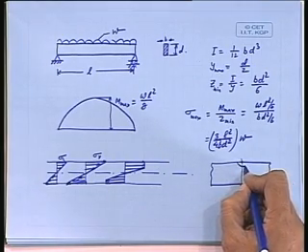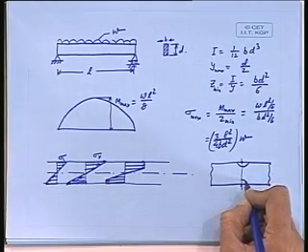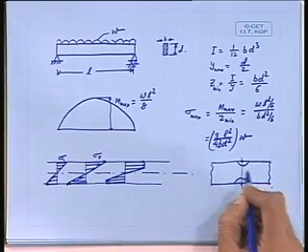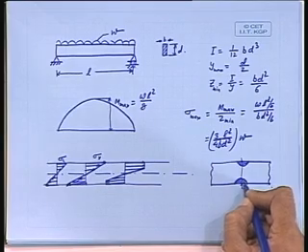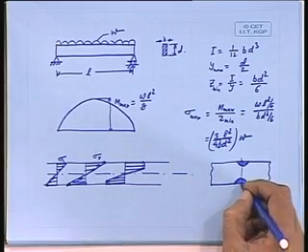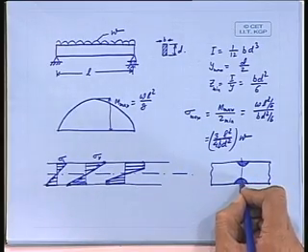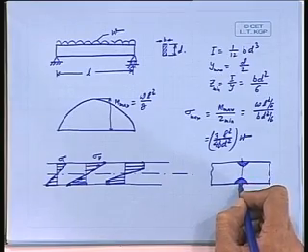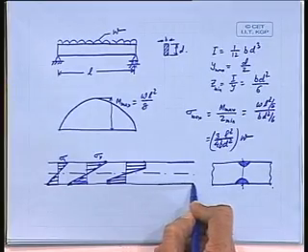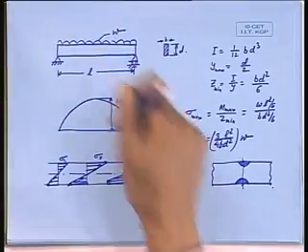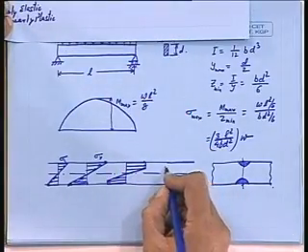Now it has penetrated down to some level and all this has become plastic region having the same stress value of sigma Y, whereas this core is still elastic, and I can still imagine that this particular core can further take the load. And if I further increase the load here, then what happens?